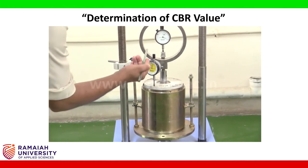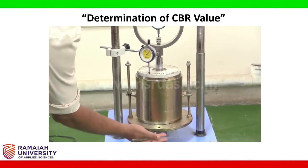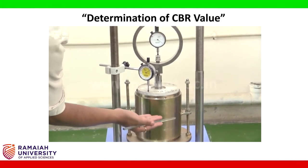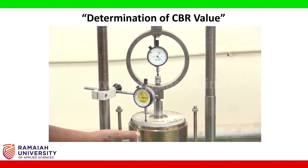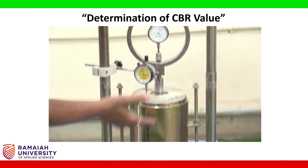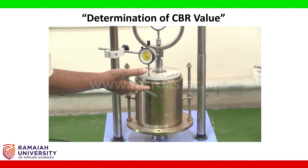You can see that the moment I switch on the knob, the base starts rising, thereby pressing the specimen against this reaction frame. Apply a sufficient load on the specimen as a seating load of approximately 4 kilos.